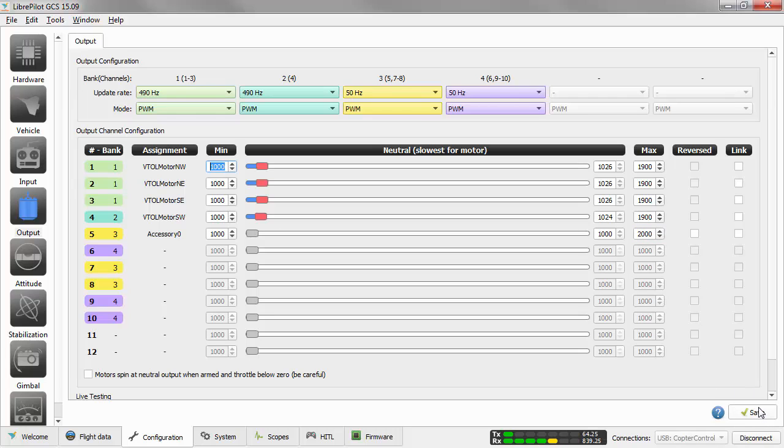And then you can point the camera almost straight down, which allows you to see quite a bit when you're in a hover. We also want to make sure that the most vertical position is the standard straightforward position. I'm not going to worry about looking up at all in this case. So I'm going to save it at 1200.